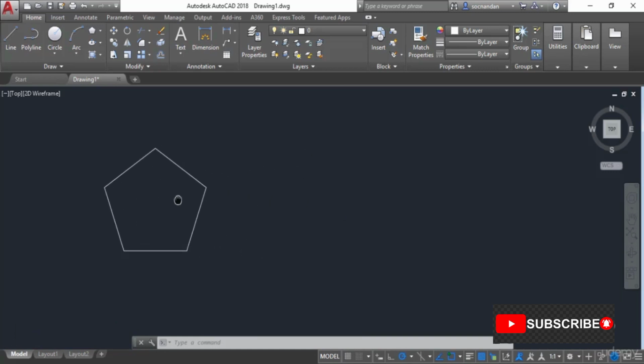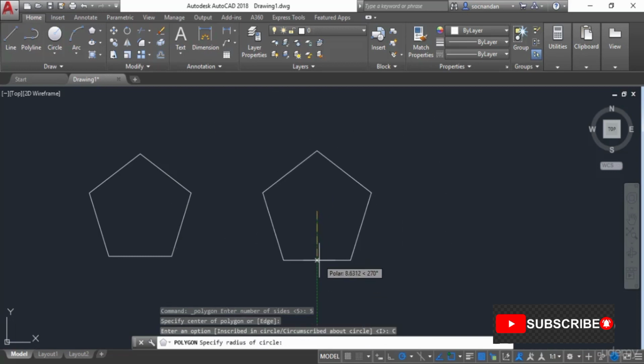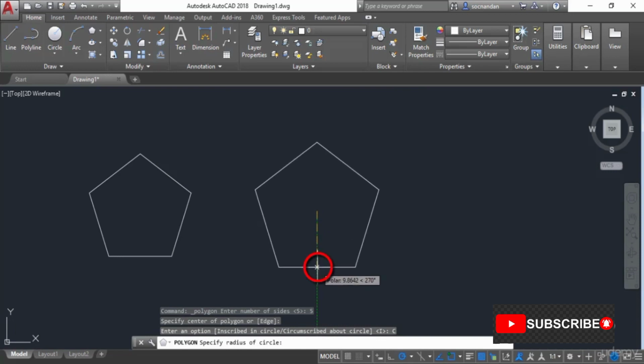So now let's move it here, and let's select the polygon tool again, and once again I'll enter 5 as number of sides, and now specify the center point, and now I'll select circumscribed about circle in this case. And now you'll notice that instead of vertices, the cursor is now at the midpoint of the line segment. Or you can say that the cursor is at the midpoint of one of the sides of this polygon.